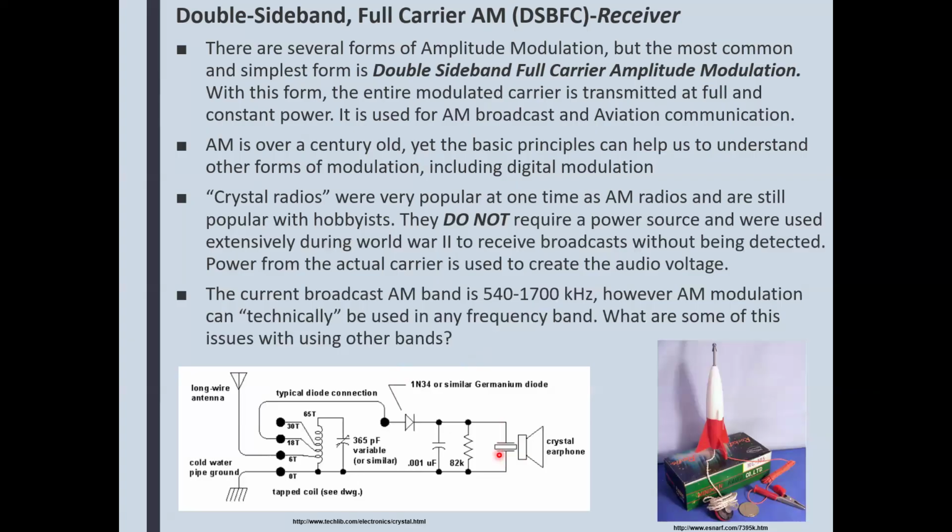And the crystal radio, it would have an antenna, it would have some sort of a tank circuit to detect, or you can tune to whatever frequency. You can regulate the coil, and you can regulate the capacitor, and you can have the diode just to provide the nonlinearity and rectify things. And maybe here's a tone control, but you can actually have this without those.